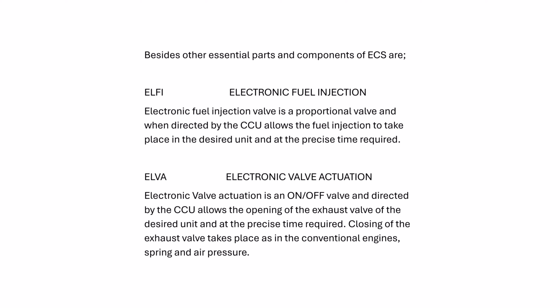Let me tell you one thing, a secret, not a secret. In these engines, you can control the timing of the exhaust valve. You can open the exhaust valve a little late, or open the exhaust early, though normally that is not allowed. You cannot advance the timing of exhaust valve opening. Opening can be delayed by, of course, 1 or 2 degrees. Closing of the exhaust valve you can change.